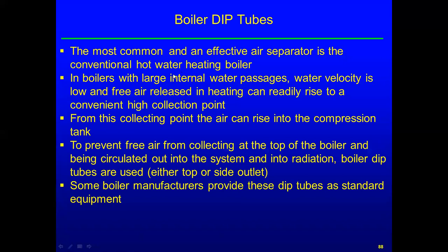And these types of boilers typically or often have large internal water passages, water velocity is low, free air is released in heating and can rise to a convenient point of collection. From this collection point, air can rise into the compression tank or be eliminated.